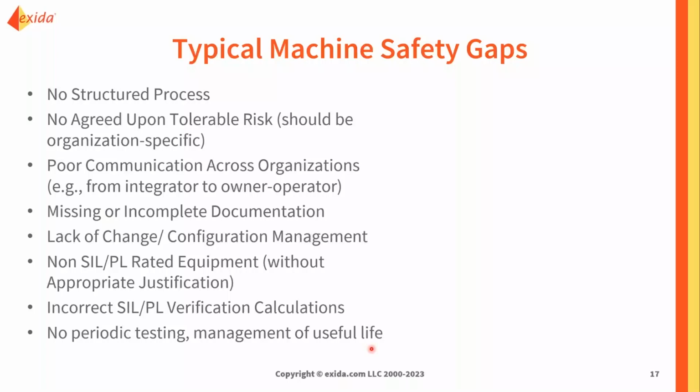Additionally, even though ISO 13849 doesn't require testing of all safety functions, if you do have hydraulic components or other pieces that can have things like stiction and additional failure modes that occur if it sits for a long period of time, there are actually requirements in 13849 that those need to be stroke tested at least every 2 weeks in order for the failure rates given as estimates and other approximations to be valid.